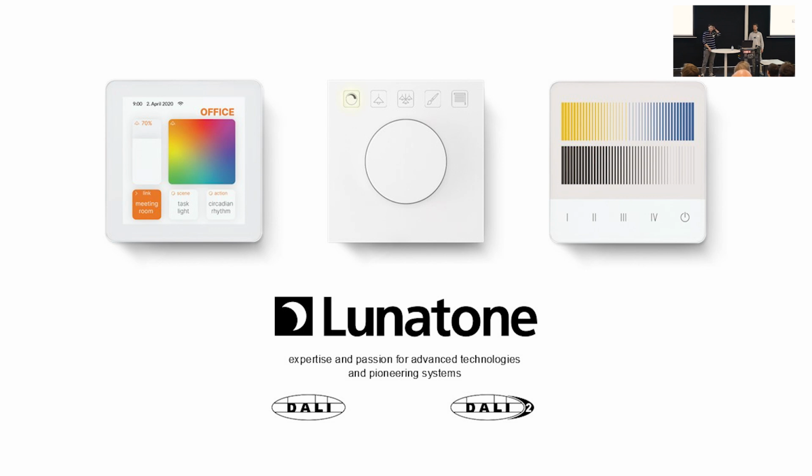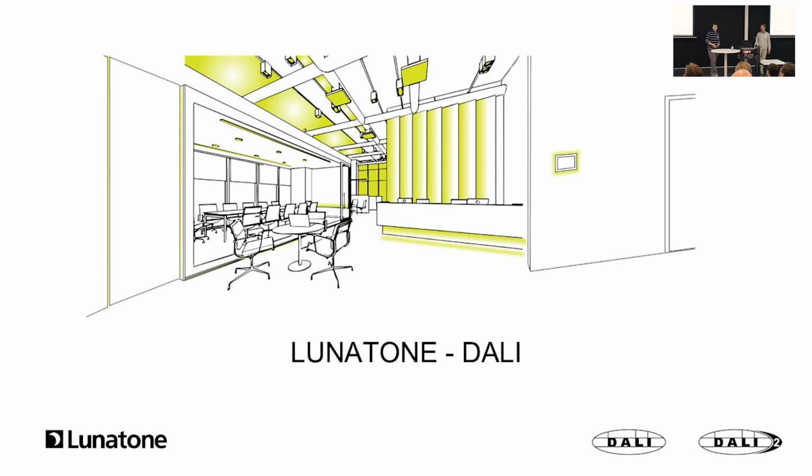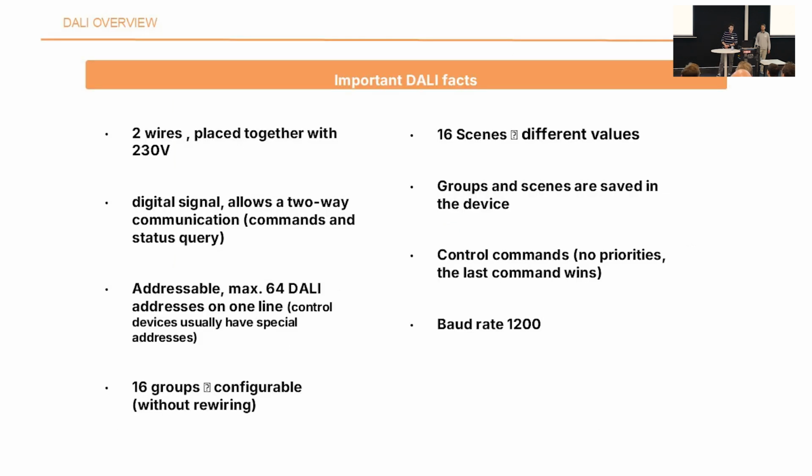And now we start with the presentation about DALI. So, first of all, we want to talk about the DALI system in general, just some important facts for you all. So DALI is a two-wire digital signal bus, meaning it can be placed together with the 230 volts cables. It supports 16 groups and 16 scenes, and the baud rate is 1200, which is pretty low, but it's consistent.